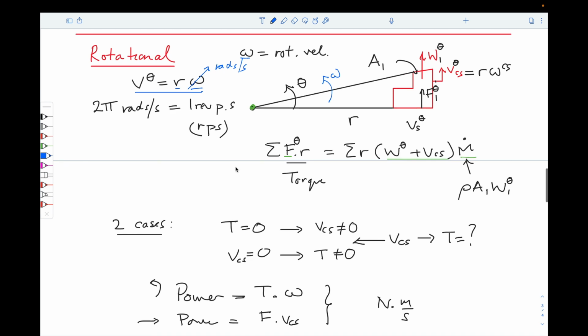Again, we can solve the problem for the fluid coming out of the vane. We have two end-member conditions. We can either let the vane rotate, in which case the force that we apply to the vane, which is positive in the same direction as this velocity, that's our positive coordinate direction here. So if the force is 0, then from solving this equation, this will be going at a maximum velocity, which is typically equal to the negative of the outflow velocity. When these are negative of each other, this will be a force that's 0, or a torque that's 0.